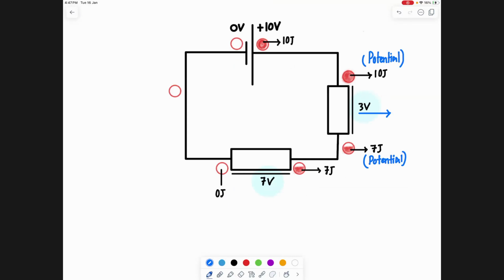And once you do practicals, you'll find there's a red wire and there's a black wire. The black wire is the negative terminal of the voltmeter. The red wire is the positive terminal of the voltmeter. When you take the two wires and place them in your circuit, charge enters the black wire and charge enters the red wire. Inside there is a circuit that measures the potential of the black wire, measures the potential of the red wire, and what does it show? The difference.